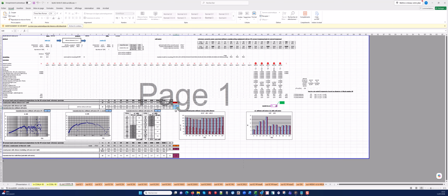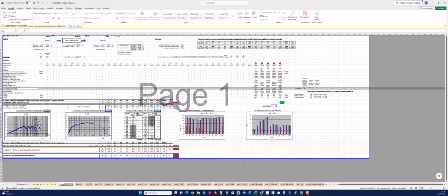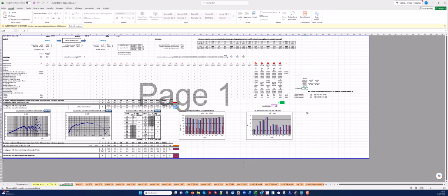LW1 and delta L without consideration of self-noise or with consideration of self-noise are illustrating the situation with the silencer accounting the self-noise LW. The total pressure loss is also computed for each element and also as the total for the silencer.